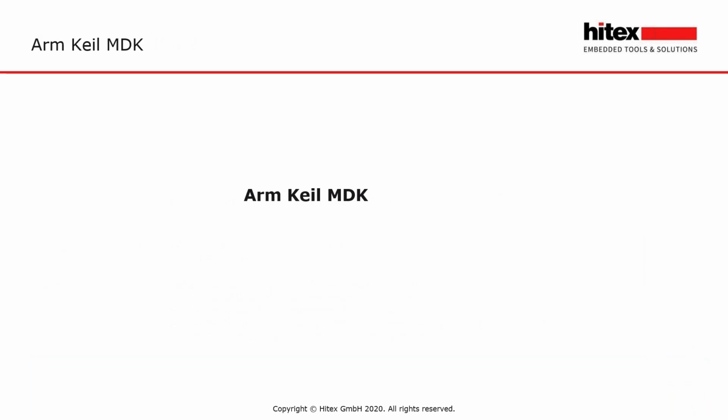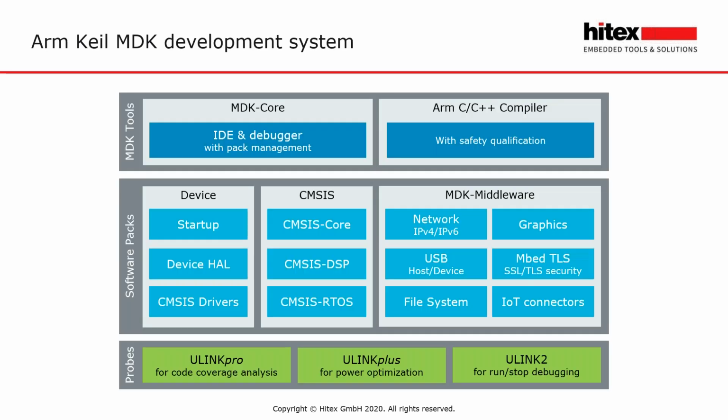So all of this, as I mentioned, sits within the Keil MDK. This is the standard IDE that's available. It includes the Microvision IDE and its debugger, and software packs that were provided by the silicon vendor. Ideally, if they have a safety related device, they'll provide safety certified libraries and drivers. We then have CMSIS core, which will be safety certified to sit on top of that.